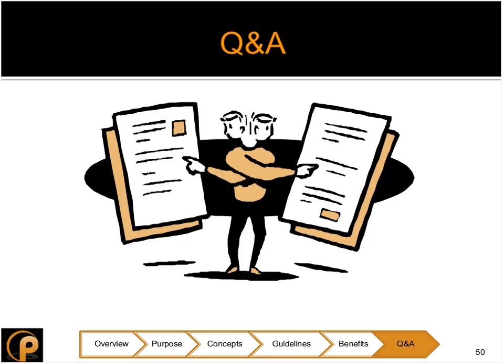Okay, thank you. What are the maintenance requirements for a pressure relief valve? Pressure relief valve maintenance requirements may come from the code itself. They may tell you that you need to inspect at regular intervals to make sure that there is no damage, that the soft goods are in good repair, or you may have your own internal company standards which dictate how often you want to inspect, repair, and replace relief devices. They're not things that you can leave alone and expect to work forever. They are prone to wearing out and breaking down, and so they need to be inspected.